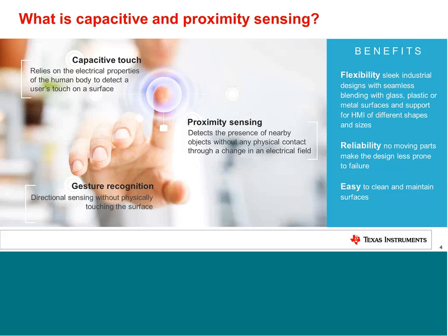So moving forward, what is capacitive sensing? Capacitive sensing is using the principles of capacitance in applications such as proximity sensing and buttons. Basically, you have a charged electrode built into your PCB, and you wave your hand near the PCB, and you're grounded. So you're changing the capacitance field, the E field, associated with that electrode, and you're using that to determine whether a person is in contact with the electrode or not.